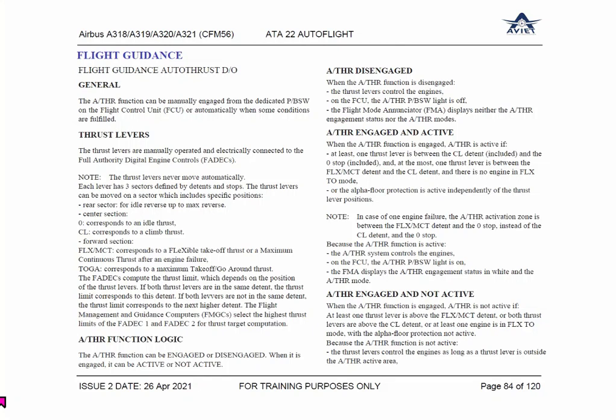Autopilot, you have studied, when the autopilot is engaged, it becomes active 5 seconds after liftoff or 50 feet after liftoff. But if you want to use the autopilot and the engine is started, it will disengage. I hope you have studied this in autopilot.